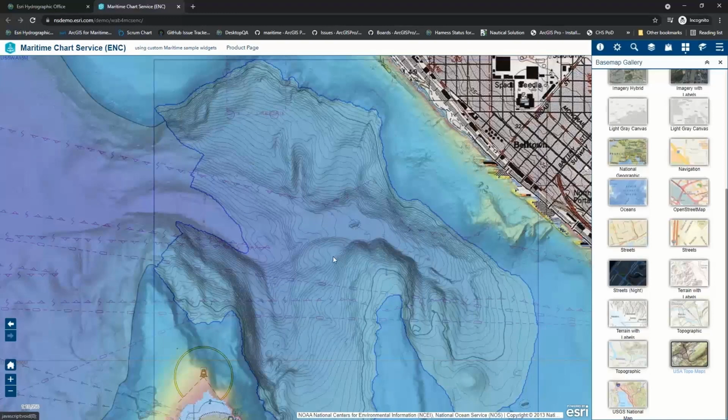So here you can see how you can take this data all the way from XYZ, create bathymetric ENCs or updated S57 ENC, inland ENC or S-101 data sets. You can automate that workflow to whatever degree you're comfortable with, because all of the tools that we used here are geoprocessing tools, so they can be strung together.